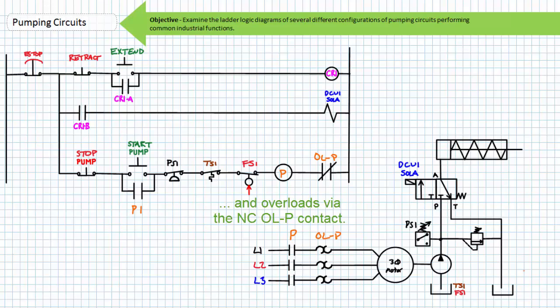Notice, however, if an operator were to press and release start pump, and the pump didn't start, there could be several reasons why, and an operator could only guess at the reason. Is the e-stop open? The stop pump push button stuck open? The start pump push button not closing? The motor overloaded? The pressure too high? The temperature too high? Or is the fluid too low?